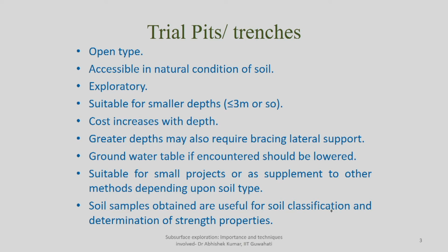a fairly good amount of idea about the site, soil condition, soil depth, and if possible the water table if you encounter it, because as I mentioned earlier, these kinds of investigation are more suitable for 3 meters or so depth. So, if you have a water table at that depth, which is very likely to occur in many locations, you can even report that part.